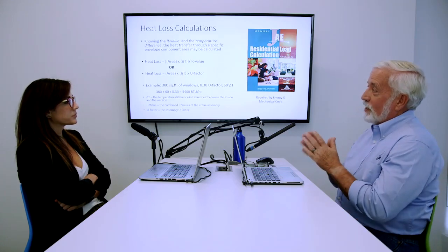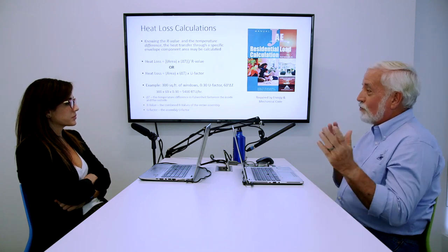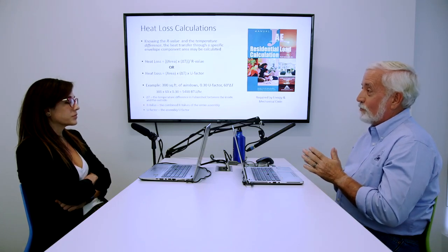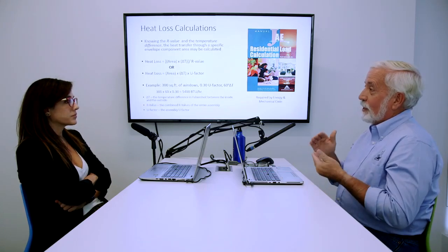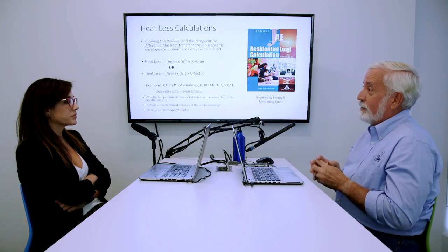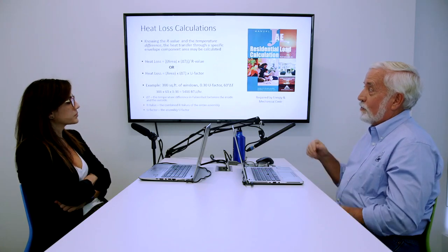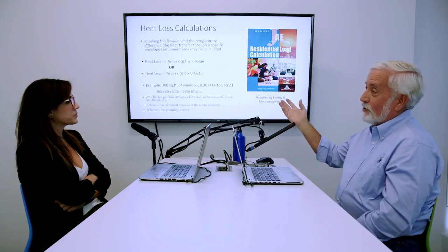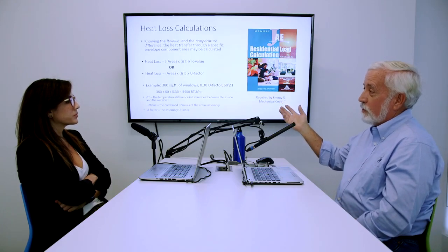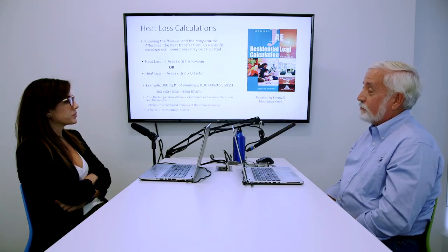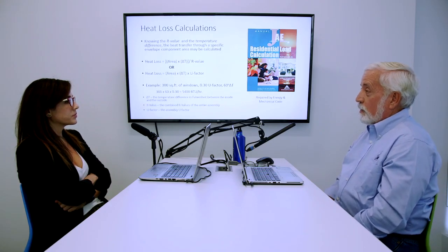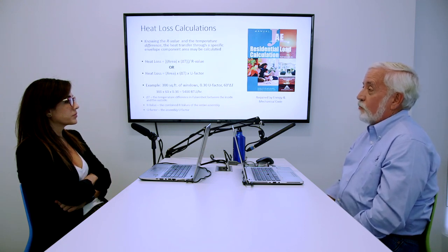If you minimize the amount of window you have, so you don't have huge amounts of window, and then you make really good walls that are like R24 or something like that, you can end up with a pretty low load calculation, because windows are going to be your biggest. Your walls might be just 1,000 BTUs or 1,200 BTUs for all your walls. And it's not uncommon to see a 1,500 square foot house come up with a total heat loss of under 20,000 BTUs, maybe in the 15 to 16,000 BTUs.